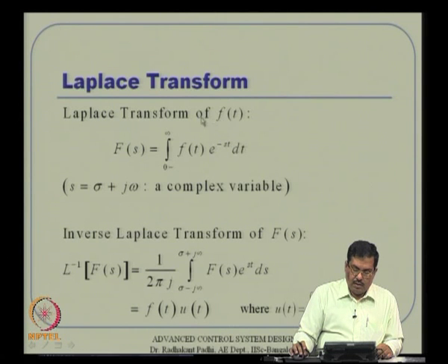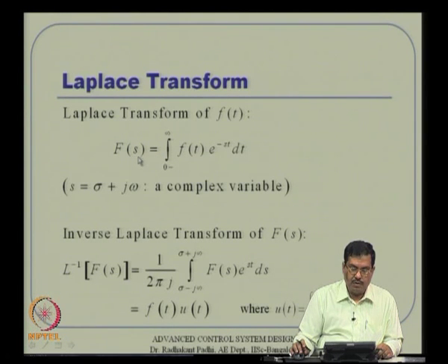When you take the Laplace transform of a time varying function, essentially it gives us a frequency dependent function, where s can be treated as a complex frequency. Then suppose we already know F of s, we can talk about the inverse Laplace transform. Essentially we are attempting to get back f of t. The very fact that these two functions are uniquely defined for t greater than 0 makes our life much easier, especially in linear control systems, especially classical control systems.